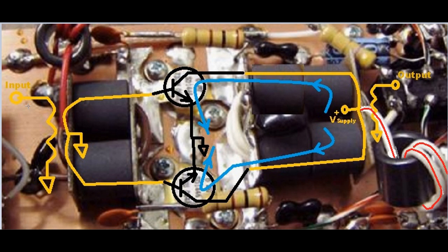So we see on the left the input RF ferrite transformer. Remember, the winding going through the air gap is the single-ended. That's the brown wire here that we see. That's the input winding. And then we know that the copper tubes, which go through the stack pole, through the ferrites to the solid back wall, which is the center tap point, and then back out through the other copper tube connecting to the two transistor bases, is the one-turn center tapped winding, as you can see here on the input transformer. Then we go through our mirror image push-pull transistors.